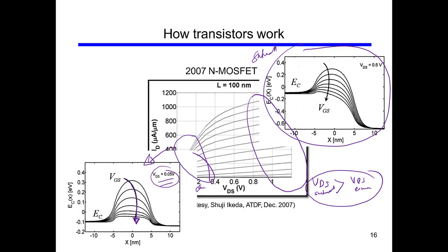You see the value here, and the VDS saturated then starts somewhere here, so it is above here. As the drain is at higher potential, it will lower the Fermi levels down on the drain side, and the shape of the potential barrier changes. So this is the shape in the linear region, and this is the shape in the saturated region.